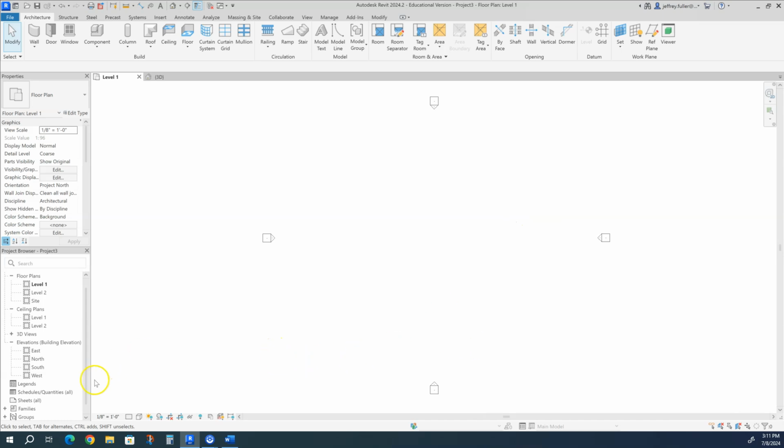And let's see, down at the bottom here, this is where you set your scale, right here at the very bottom left. So I can click on that and set my scale. A lot of times I'll start out using this scale just because it's there. But you really want to be working, especially when you get down to doing your annotations, in this scale: 1/4 inch equals 1 foot. That's the scale you want to use. So when you turn in your work, this is for my students, it must be in 1/4 inch equals 1 foot. You can see how that made the elevation markers a little bit smaller.